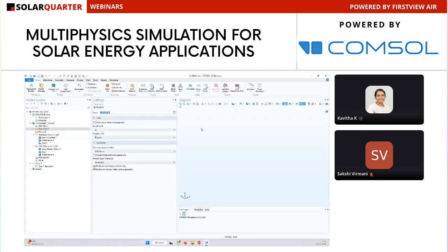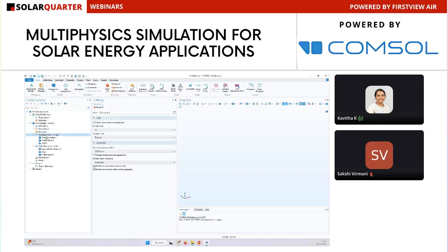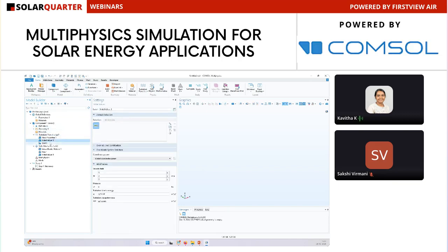So this is the COMSOL desktop user interface. You have three main windows here. Towards the left, you have the model builder. Towards the right, you have the graphics window where you can visualize your geometry, mesh, and the results. In the bottom, you have the information window where you can see the progress of your simulation logs, or if you want to evaluate the results in the form of a table, it gets displayed here. And also you have a settings window. If you are going to set up your model using different nodes in the model builder, each node will have the appropriate settings displayed in the settings window.